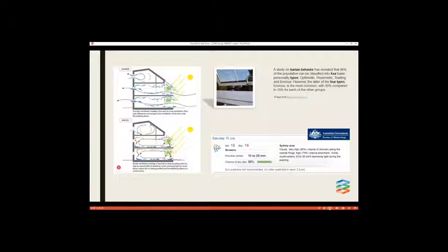But if the wind stops, if there is no wind, how do you get that air to flow through the building? It's notorious for not following the directions that we've drawn on the plans. Particularly if there's no wind outside, you open the windows, there's not going to be any wind inside either. Those things are really important to understand, and to rely on human behaviour. Are we going to make sure that everyone is going to open those windows when they're supposed to ventilate their buildings? Not necessarily.